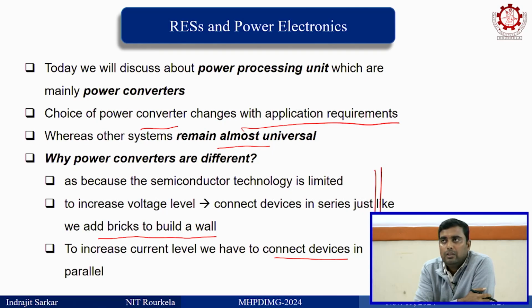For that, you need high reactive power at the source and load end to make the thyristor commutate. Then people thought, if we are coming up with multi-level converters, why not use them for HVDC? Because the features of VSC, voltage source converters, are far more than those of current source converters like thyristor converters. Those are current source converters.